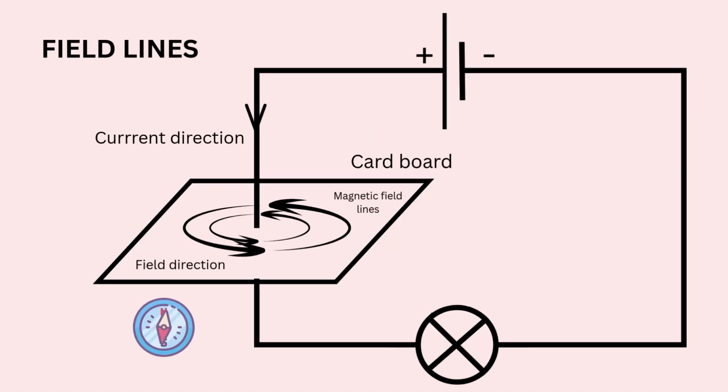We know there is a magnetic field around a current carrying wire. When a small current, say 2 ampere, is passed through the wire, a weak magnetic field is produced. If we increase the current, say, to 20 ampere, the field is strong enough to be detected by the iron filings on the cardboard. The pattern formed by the iron filings shows field lines like circles centered about the wire. The direction of field at different points can be found using a plotting compass. If the direction of current is reversed, the field direction is also reversed, but the field pattern is otherwise unchanged.